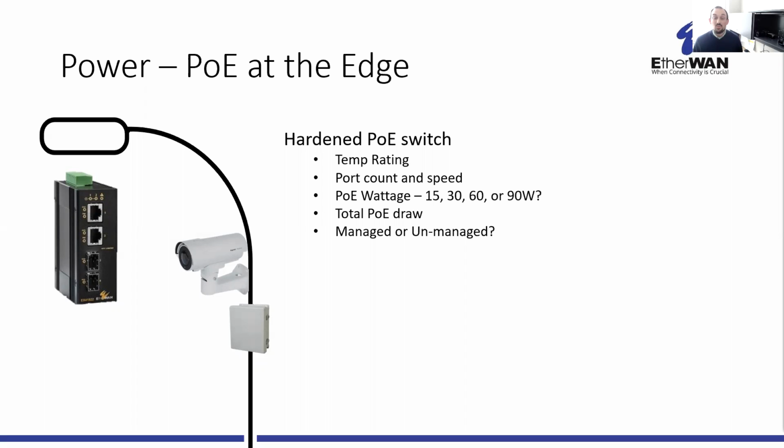That's important too, right? If we don't size that PoE switch with the right total pool, well then as these devices are turning on or heaters are kicking on, stuff might turn off. That could be bad news. And then ultimately, one of the things we need to consider picking our hardened switch, do we want it to be managed or not?